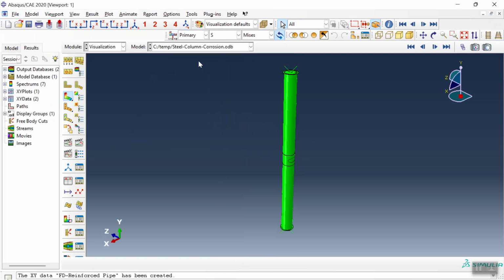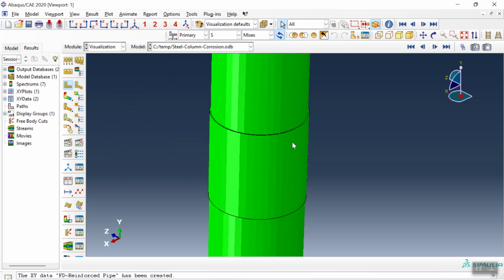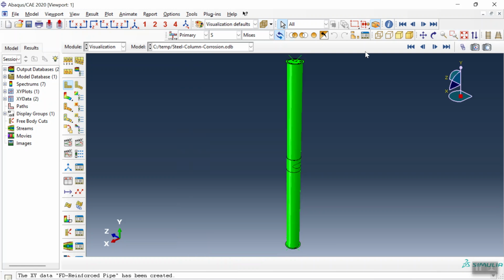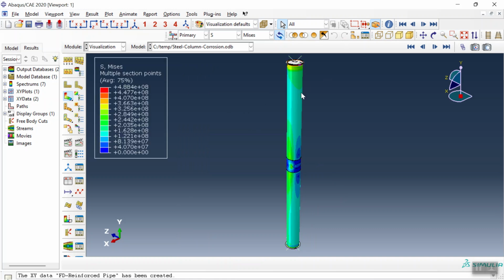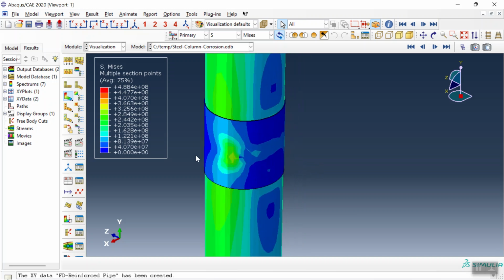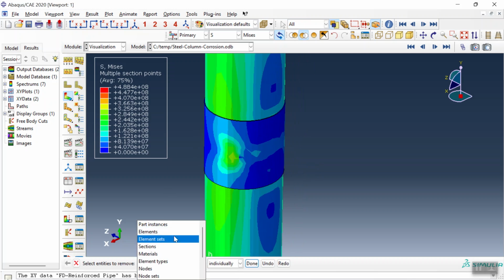And in the second model, we used CFRP. Where is it? See here, at the middle, we use a CFRP as a reinforcement to change the location of the critical zone. And if I click on this, at the same situation, you can see we don't have buckling here or the maximum stress. Here, let me remove the CFRP.